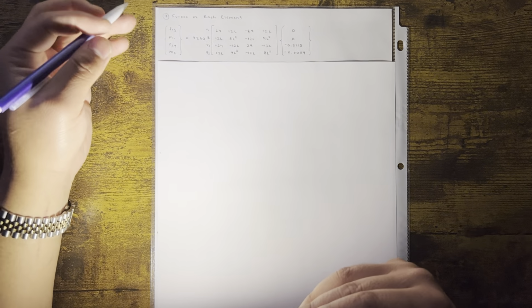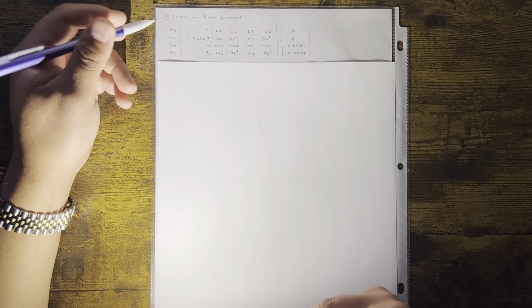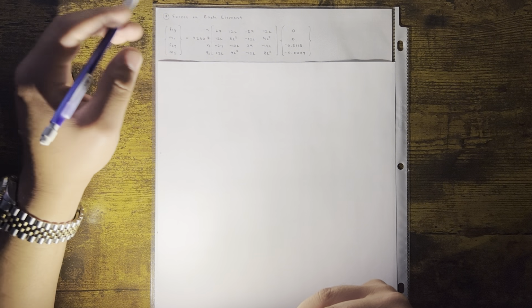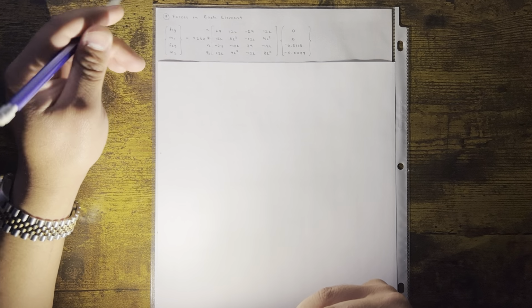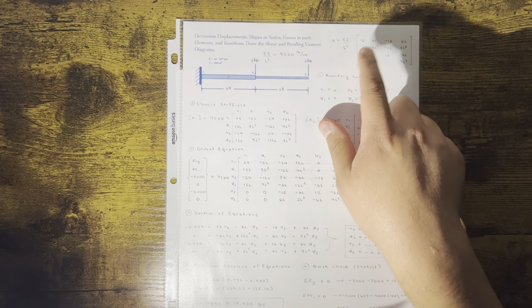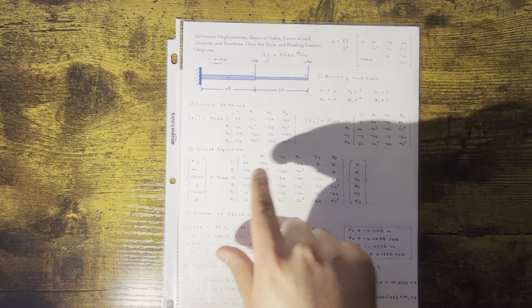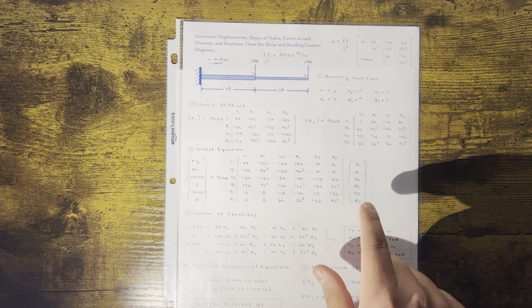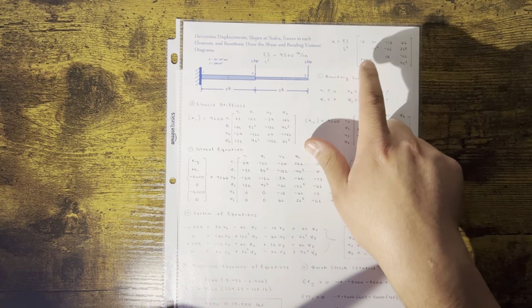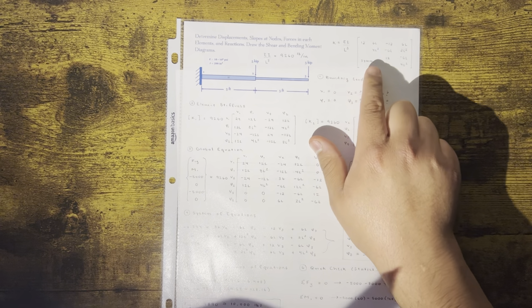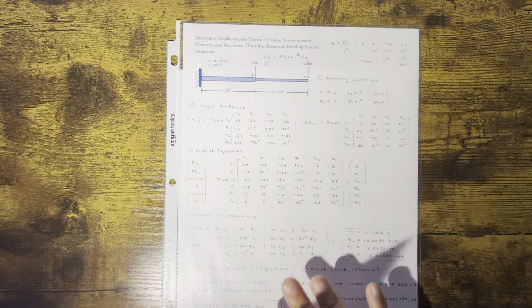So now the next step is to get the forces in each element. This is easy to do. At this point, you just start using the same stiffness values that you were getting for this side right here. My bad, I've got the flashlight in my other hand. But you use this K matrix to solve for the forces in each element. You always use the K. In all of my problems, I put a K matrix up here, and it's just the basic 12 4L squared, 12 4L squared. That's the one you use when you start solving this stuff.